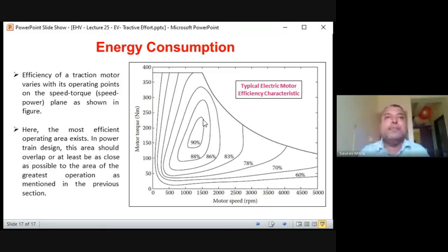We should not think that whenever we drive the vehicle at higher speed, the vehicle gives maximum efficiency. What is meant by efficiency? Efficiency is how much energy you put into the vehicle and how much energy you get as output. The energy put in to drive the car has to overcome a lot of losses. There are mainly three kinds of losses we know. First is the gradability loss, that is, when there is an inclination. Then there is the frictional loss. Then there is the aerodynamic loss. These were the three losses we learned.